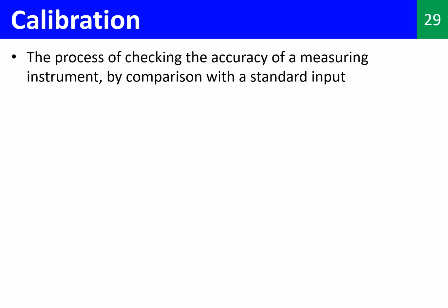What do we mean by calibration? When we use any device such as a sensor or an actuator, we have to be sure whether it functions in the required way. Say, for example, we have a temperature sensor and we want to know whether the displayed output is accurate or not. We can know that by giving it a standard or known input and observing what it outputs, right?